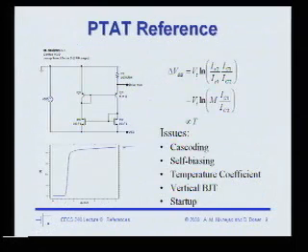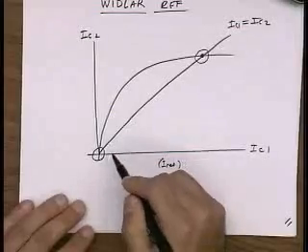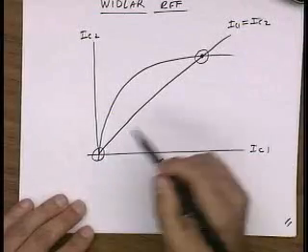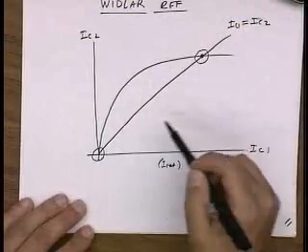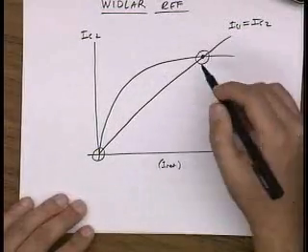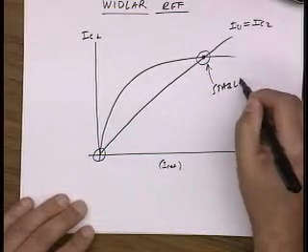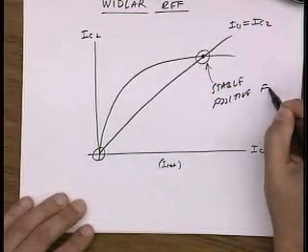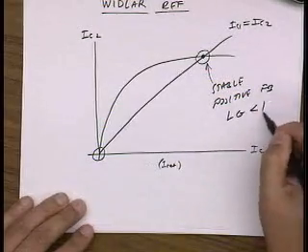Okay, so this concept of bootstrapping is really positive feedback. You're taking the output and bringing it back into the input, and that sets up a positive feedback loop. In fact, what you can show, if we come back to the notes here, is that this circuit does have positive feedback, and if you start anywhere on this curve, the circuit will kick itself and move into this stable point. So this actually is a stable point. It's positive feedback with loop gain less than 1.